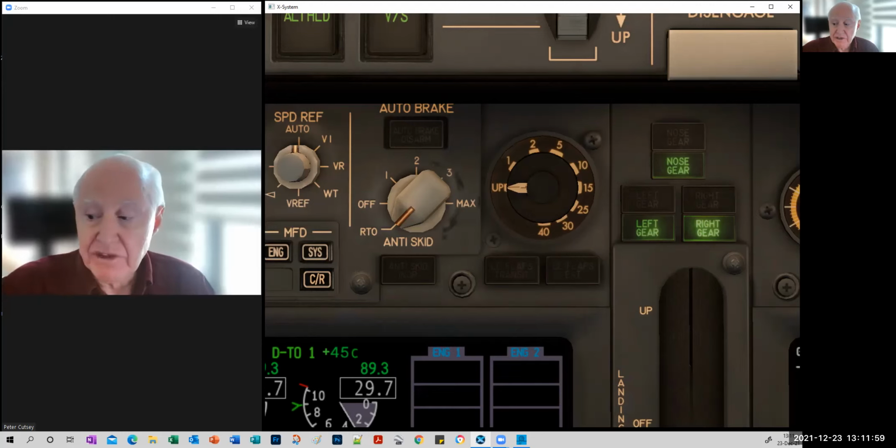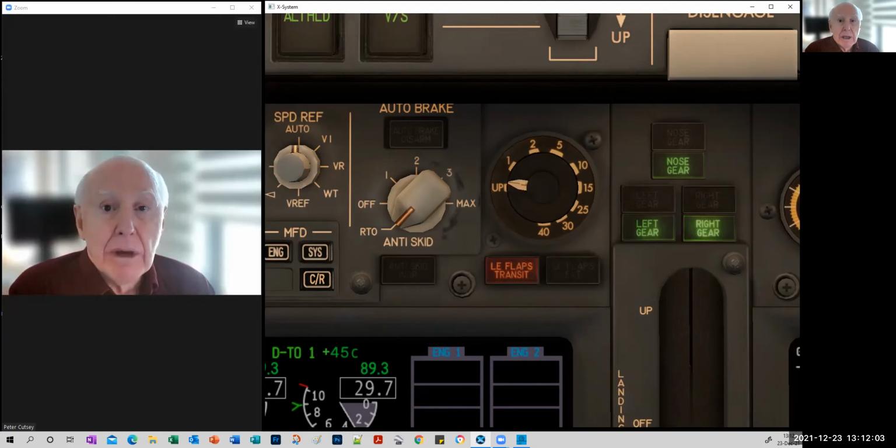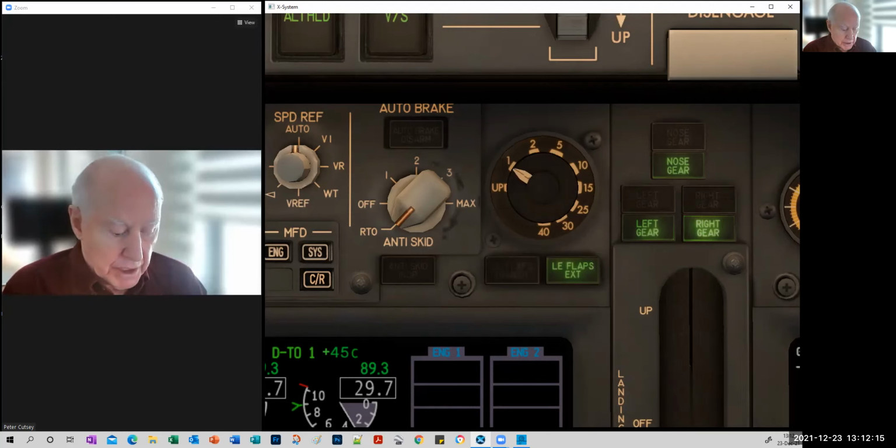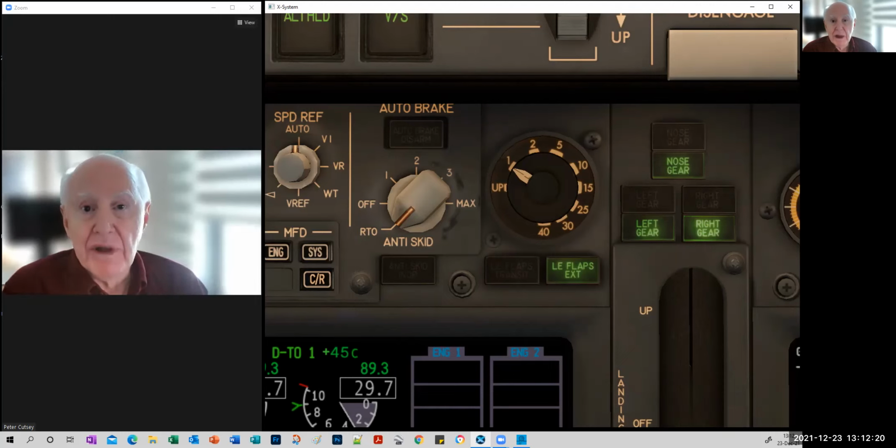So basically that's it. And when calling for flap, we normally start taking our flap when we're on vectors somewhere between 12 and 15 nautical running miles to touchdown is a good tip, as far as a good suggestion, when you're in level flight.